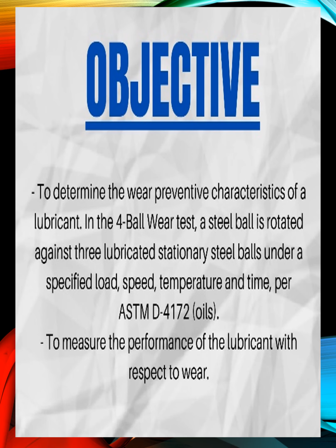So in this experiment, to achieve our objective, we use the 4-ball tester to measure the performance of a lubricant with respect to wear. During the test, the upper ball is rotated against the other three balls, which are fixed.